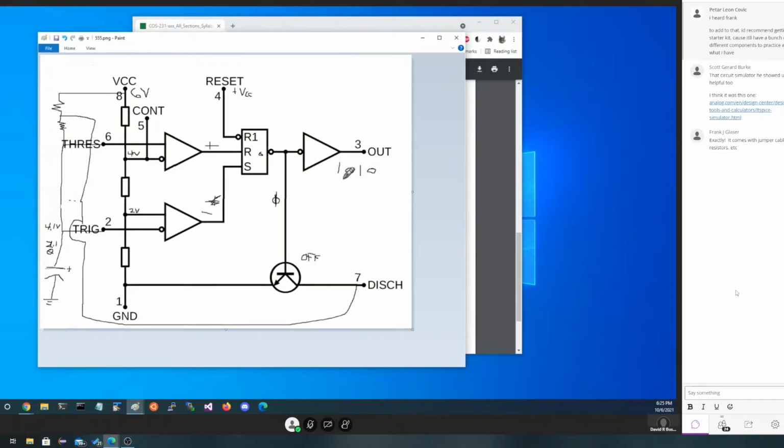What was the actual value that this was safe having on its output, either into the chip or out of the chip? Raise your hand if you remember. It was different than TTL. Remember, TTL was 400 microamps, well, actually, on the input side, well, it was output side. It was 400 microamps or 16 milliamps. What was the amount the 555 timer was able to handle?